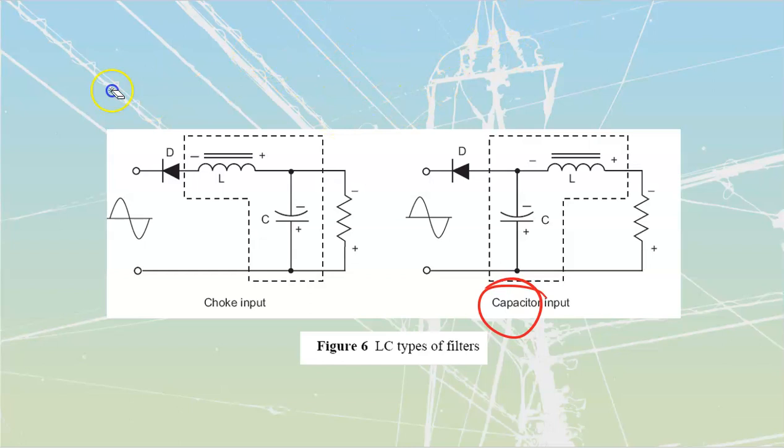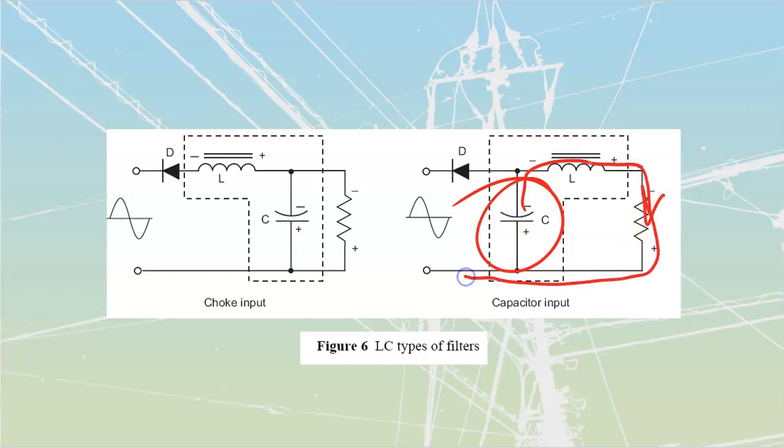If we take a look at a capacitor input, the capacitor input will have to charge all the way up to our peak value of voltage. But then when the cap discharges, it's going to run all its electrons off through this, so it's going to slow down the rate of our rise and our fall. Note that this inductor is always going to be in line with our load on this capacitor input. Whether we're feeding in from AC lines when we're forward biased, or feeding from the cap, that inductor is always in line with this, and it's either going to be seeing this voltage or the source voltage, which are going to be the same. Smooth this one out here once again.